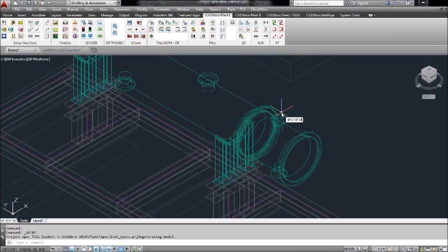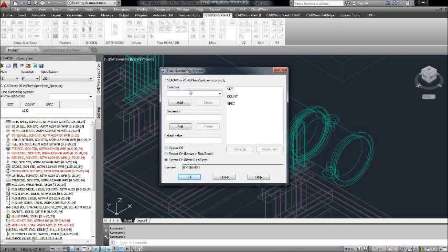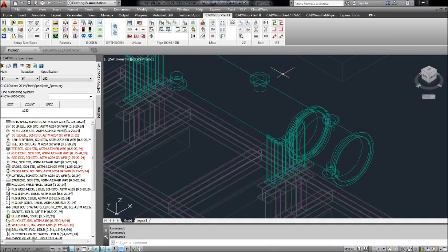Now, in CADWorx Plant Professional, your spec view palette is really your nerve center of CADWorx and the piping package. You can see over here I have my project file loaded. This is my current line number system, which is built on a schema system. I'll show you that right fast. This is built intelligently. We can add different categories to our line number and control these from a drop-down setup, so we're not manually typing in information for those things on a regular basis.